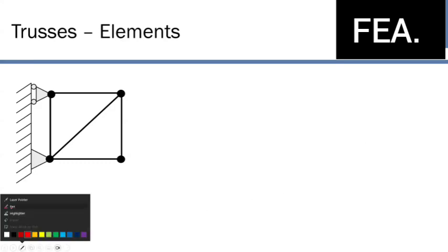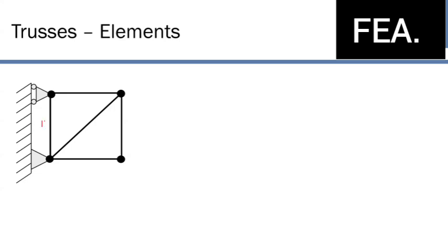All right, so let's start with numbering our elements. We're going to go with just a simple, this is 1. We're going to call this number 2, 3, 4, 5. So we numbered all our elements respectively. Now, based on the degrees of freedom of each joint, that'll determine our nodes and our degrees of freedom, generally speaking. So obviously at the pin, we can't move in this direction, so I'll just write this down as 0. Can't move in that direction. You can't move in this direction either. You can even omit it. I'll just write them as 0, but generally if you're writing something like this, you would just omit it.